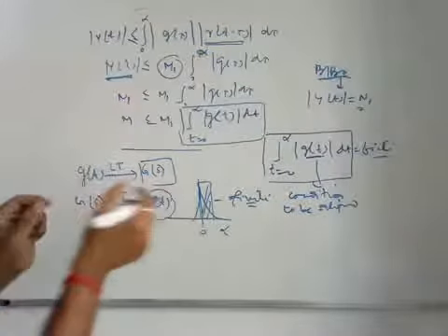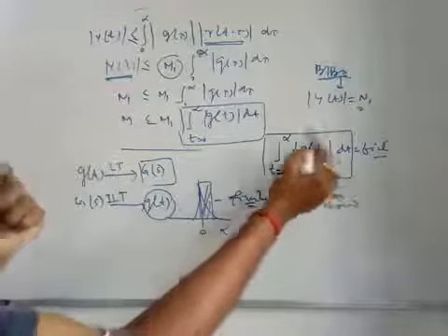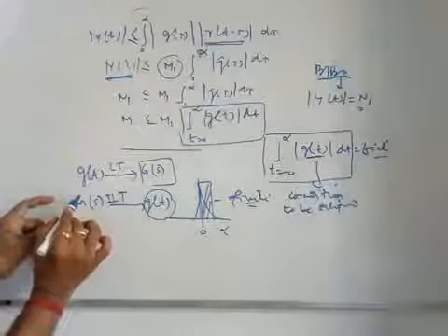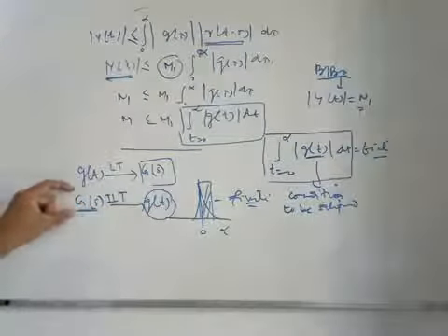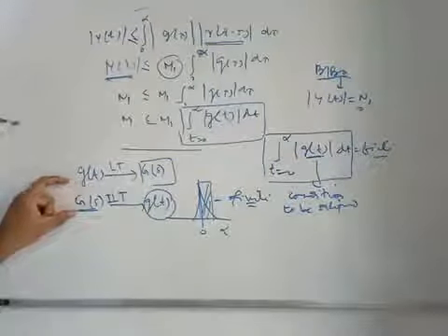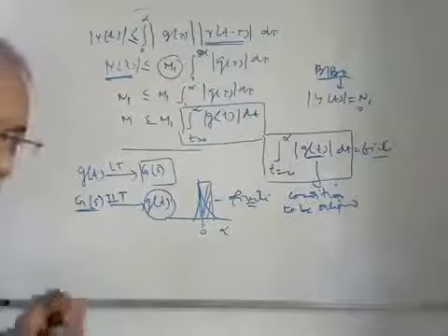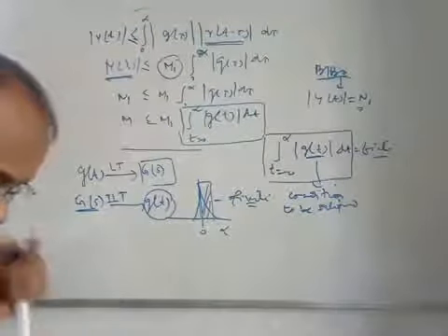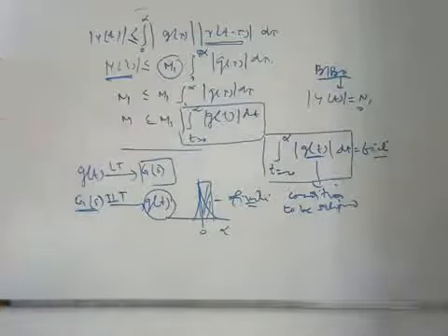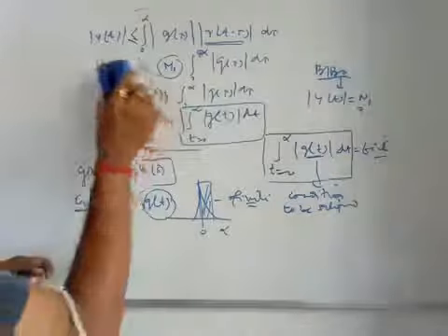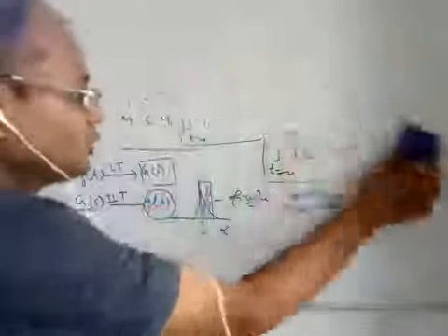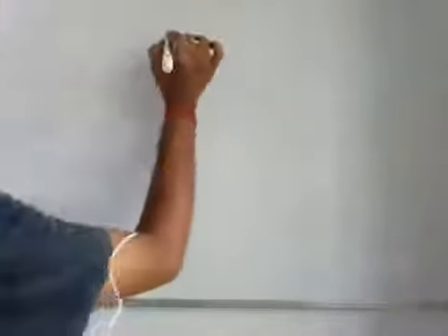That means this impulse response and its characteristic depend upon the system transfer function, that is G(s). And if the system transfer function is known, what plays the major role is the poles of the system, right? So the locations of the poles will be related to the conditions on g(tau) d tau.